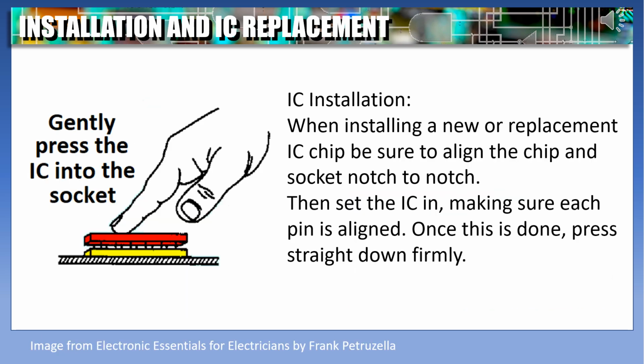When installing a new or replacement IC chip, be sure to align the chip and socket notch to notch. Then set the IC in, making sure each pin is aligned prior to pressure. Once this is done, press straight down firmly.